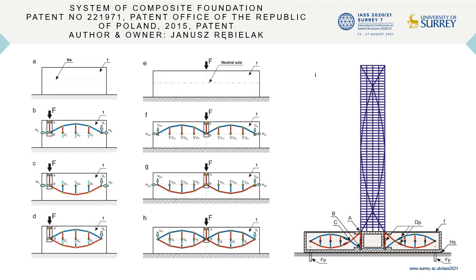In a narrow space between two horizontally located beams is arranged an intermediate structural system which is connected to these beams by means of nodes uniformly distributed along the neutral axis of the beams. The intermediate system is built of two subsystems. The first one is called the tensile construction system, while the second one is called the arch system.